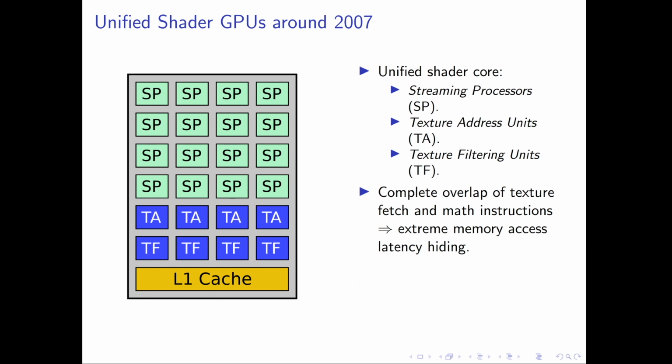in the texture image. And the design was a streaming design in a fashion that there was complete overlap between the processors that were concerned with compute and the processors that were concerned with memory accesses. And then those unified shader cores had, and also have nowadays, a shared L1 cache that our cores can access. And those architectures actually evolved quite a bit.